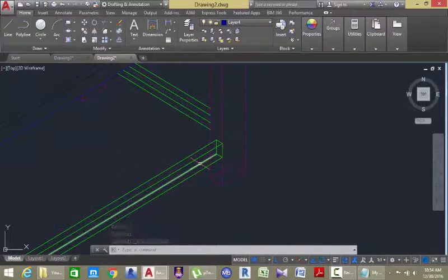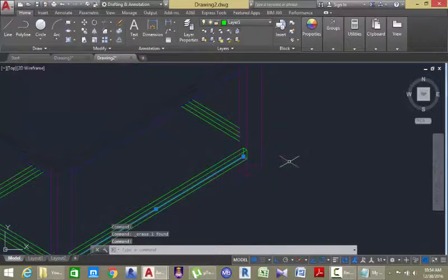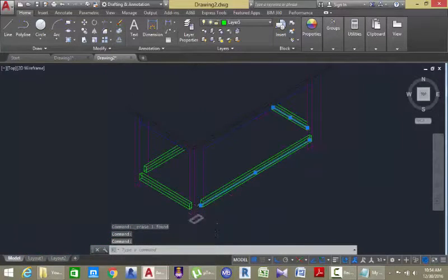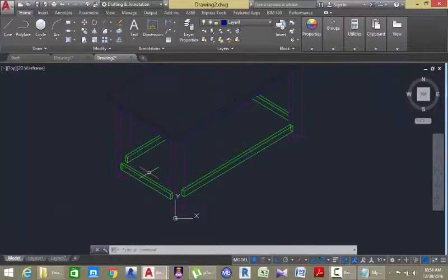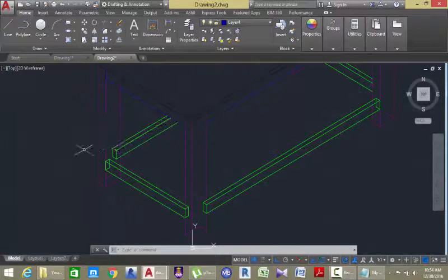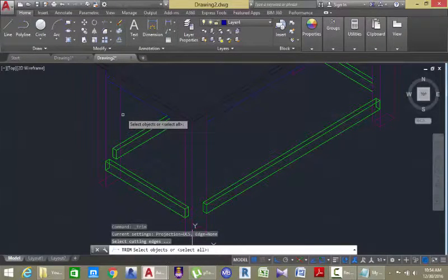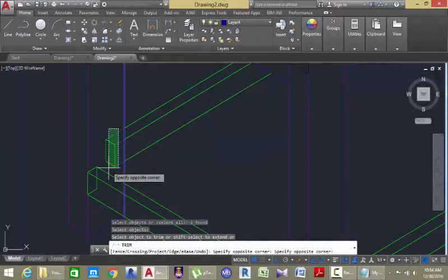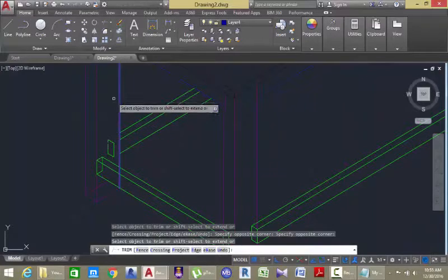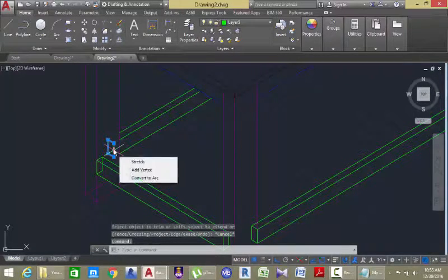Again, in the real world, you are not going to see this edge, so erase this edge. This edge. This edge. These edges are not going to be seen in the real world. Select them and erase them. Then anything that goes beyond this line is not going to be seen in the real world. Go to the Home tab, Modify panel, and select the Trim command. Select this line, press Enter. Trim all this stuff off. Press Escape. Select this rectangle and press Delete on your keyboard.